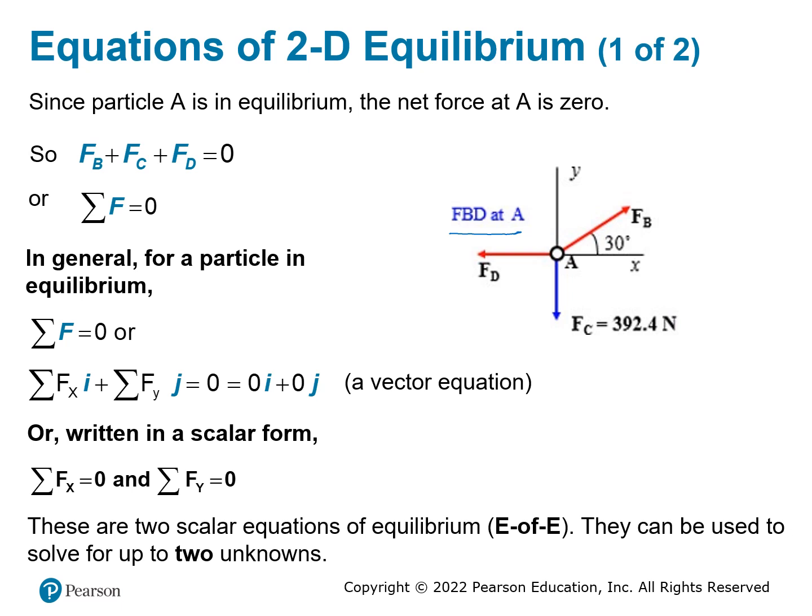Our condition is this point A is going to be a static point because the point A is not going to move. In a case you hand away at the bottom, two cables go in different directions and will hold the point A to be static. So we can use the particle in equilibrium. And we just told you when that is the situation, you have a net force equal to 0. This net force is coming from the 3 different components, the F of B, F of C, and F of D.